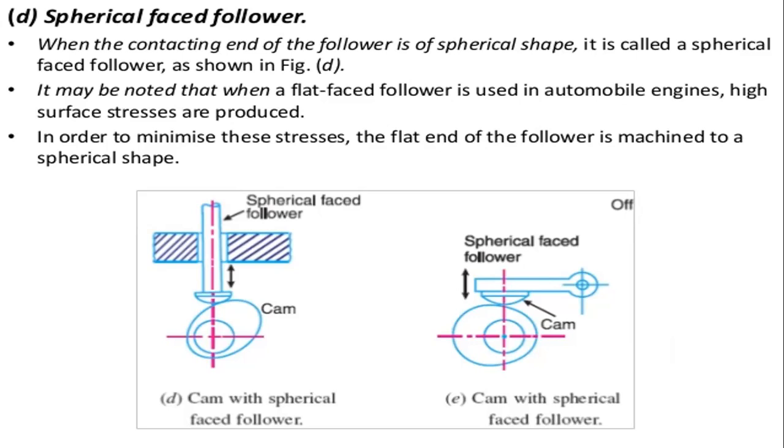It may be noted that when a flat faced follower is used in automobile engines, high surface stresses are produced. Generally these flat faced or mushroom followers are used extensively in automobile engines, and the surface stresses are produced at a very high rate.